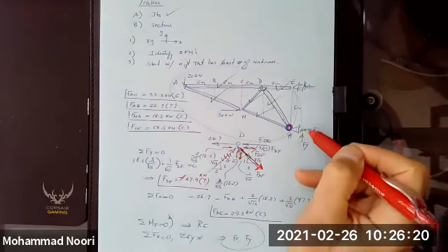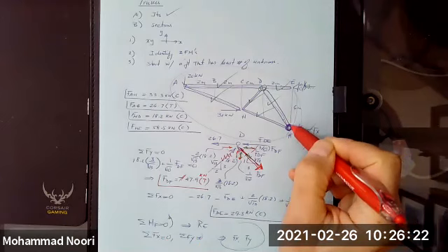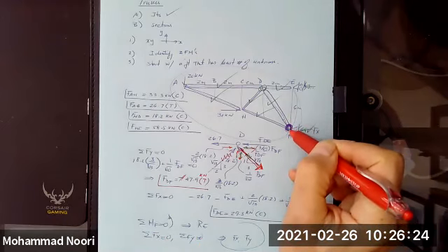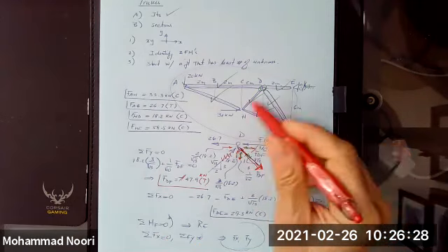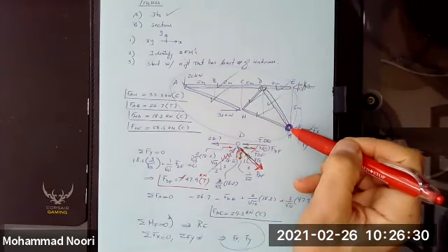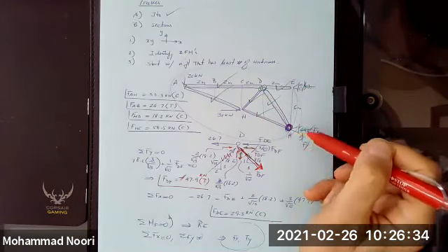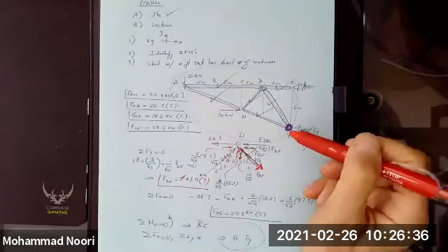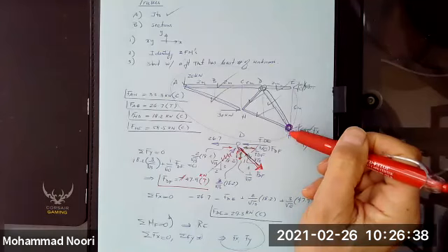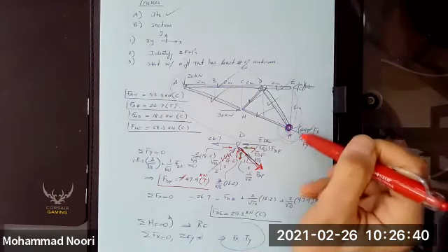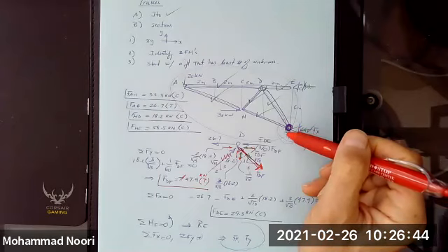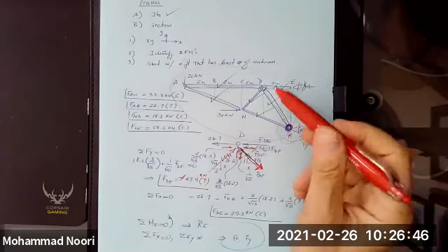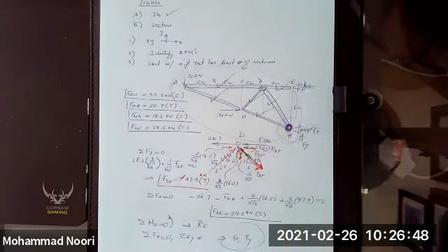So now if you have these, you look at this free body diagram that you had not used, the free body diagram of this joint. And these answers you found, for HF and DF, should satisfy the equilibrium. Should satisfy summation of forces along x and y equal to 0. That would confirm if you have correct answers.